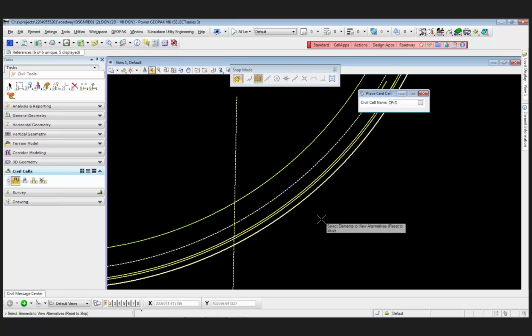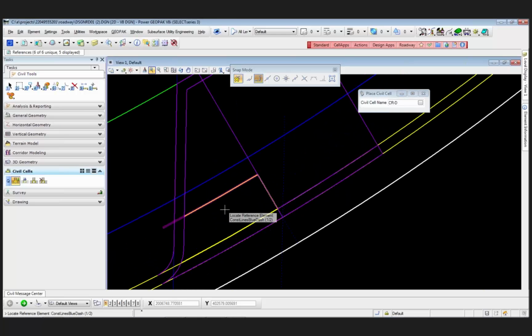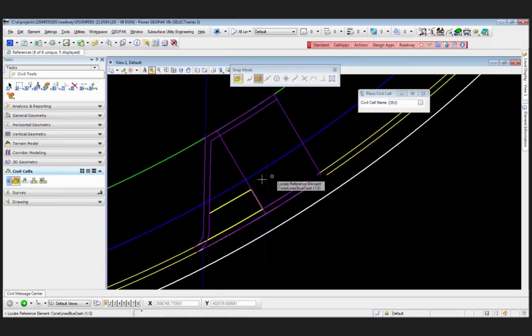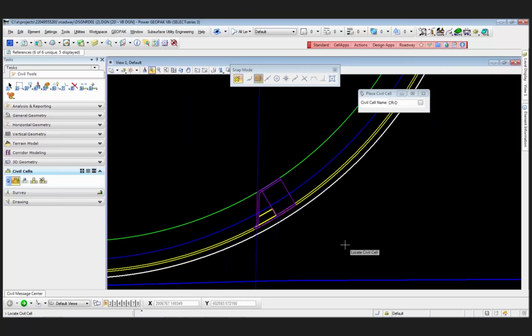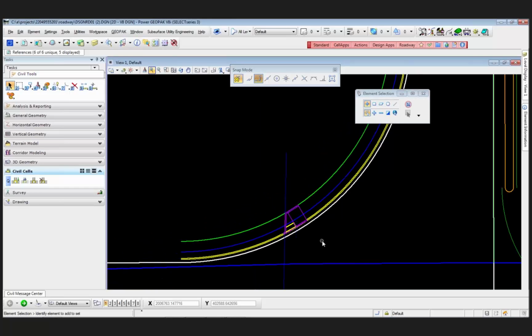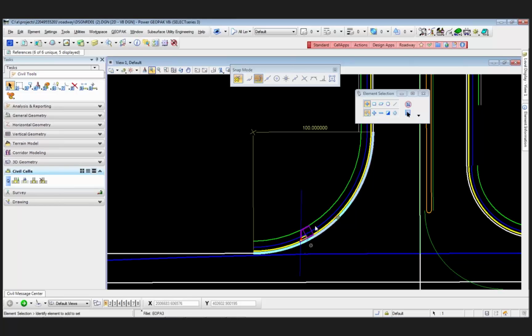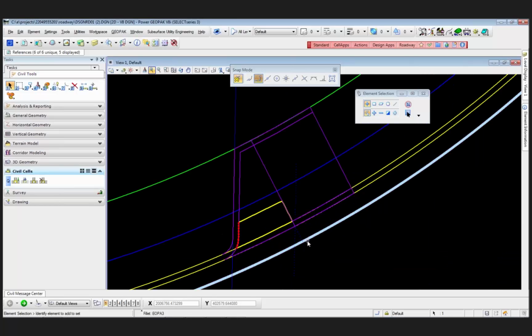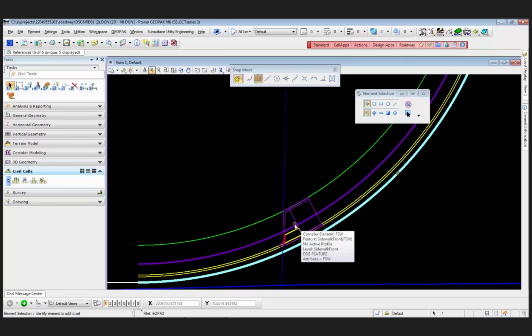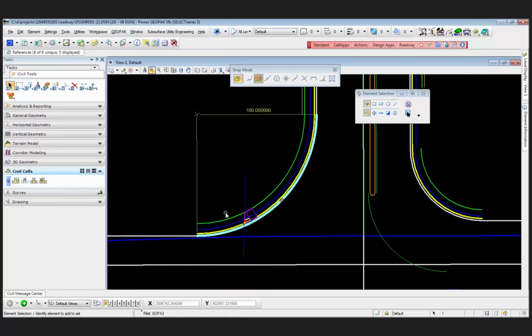And it will essentially draw in the curb ramp there for you and the pad in this case. So this would be the little truncated dome pad, and then there's your ramp configured at that orientation. And if all works correctly, if you were to change something, like let's say this had to change to a 100-foot radius, then everything is basically redrawn and reconfigured according to the way it was designed in the civil cells for everything.